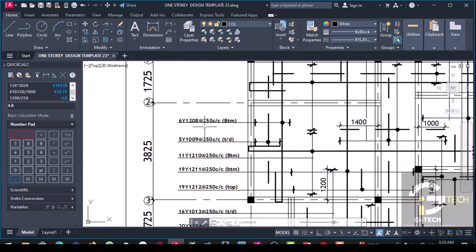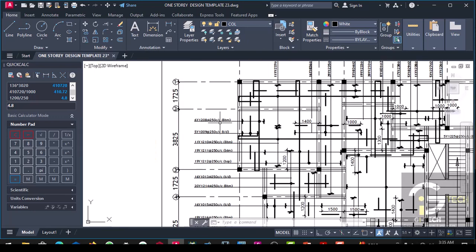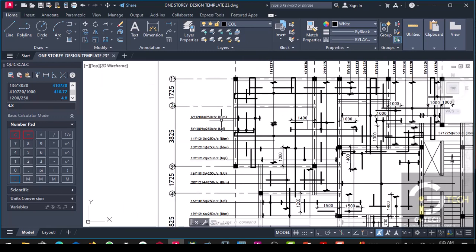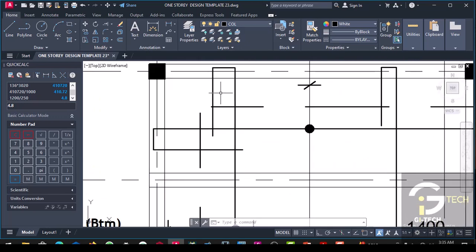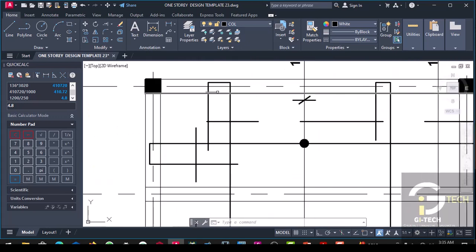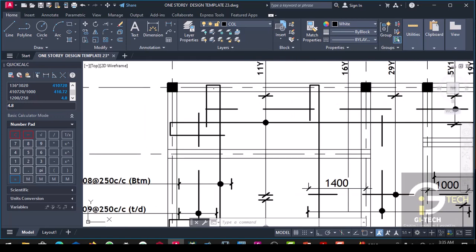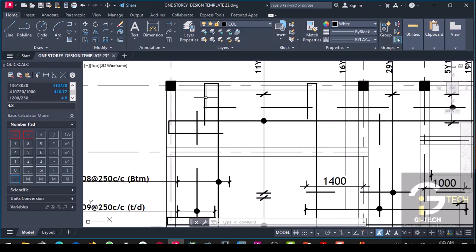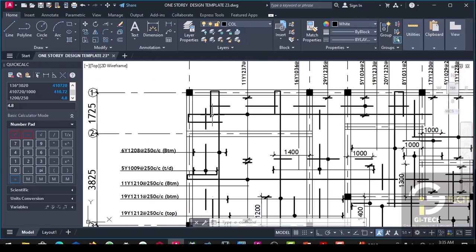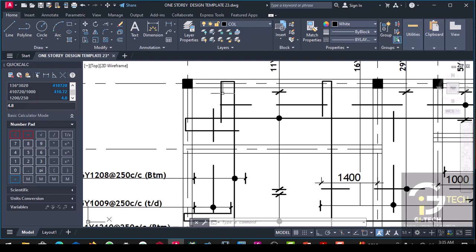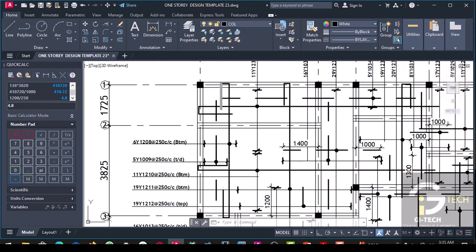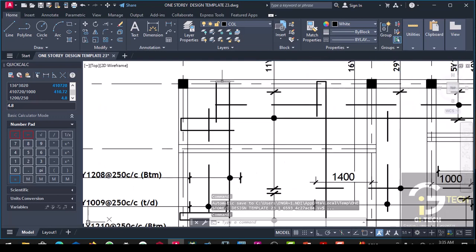Now before we continue with this, let me clarify 2 points here. Now for us to have the length of the returning bar of this continuous edge, we will multiply the adjacent length with 0.15 for us to have the length of these returning bars.